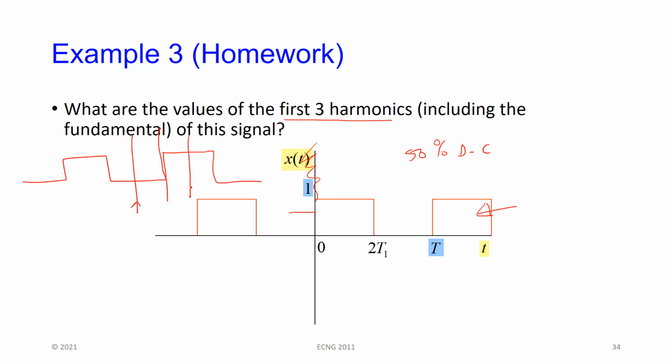What I am changing is this sort of time relationship between where I start looking at it, and what the signal is actually doing at that point in time. So if I start looking at it here, the signal does nothing and then starts to change. If I start looking at it here, the signal is already 1 when I start looking at it and then it changes. Here, which is where we started, it's 1, but it changes after just about half the period of time and then goes back and does whatever it wants. So the only thing changing is my time relationship with the signal. In other words, the phase.